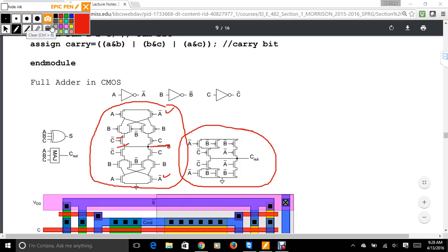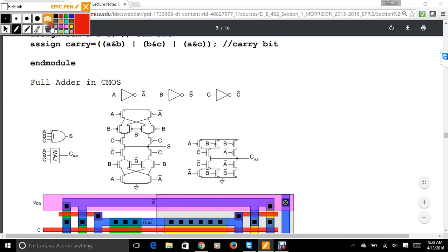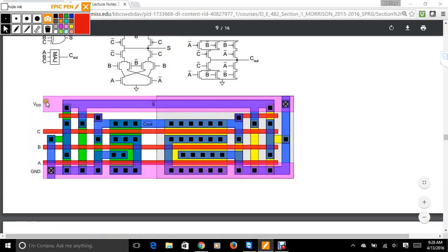And then what's actually going to happen is it's going to take your design rules. It's going to take all these, how do you actually size these transistors, everything we've learned up to this point in this course, and it'll synthesize it down to this. So you have these poly. Everything we've designed is going this way. In this case, the poly is running horizontally, A, B, and C in, and then you have your sum output.